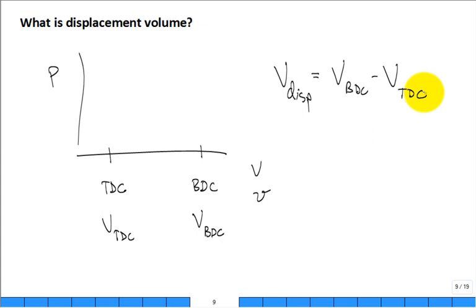So let's say I have a 2.2 liter engine, but it's 4-cylinder. Well, they're reporting 2.2 liter for the whole engine. So if I wanted my displacement volume for 1 cylinder, not too hard, take the 2.2 and divide by 4. That would give me my displacement in liters for 1 cylinder. Okay, another piece of information that we need to know is...